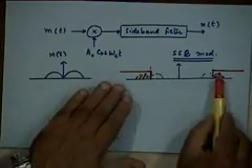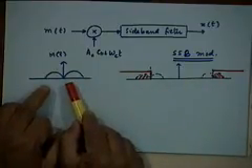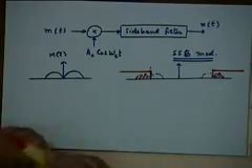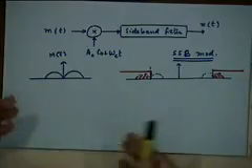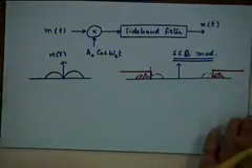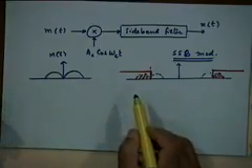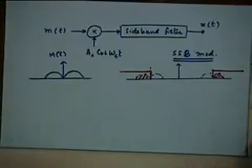Suppose we retain the upper sideband. Now how do I get this message signal back? How do I do the demodulation? Can anyone suggest? Because if I can't demodulate, then this whole exercise is a wasteful exercise. It doesn't help anything, right? What should I do as a demodulator? Any answers? The demodulator remains the same synchronous demodulator that we had for DSB-SC. Absolutely no difference.